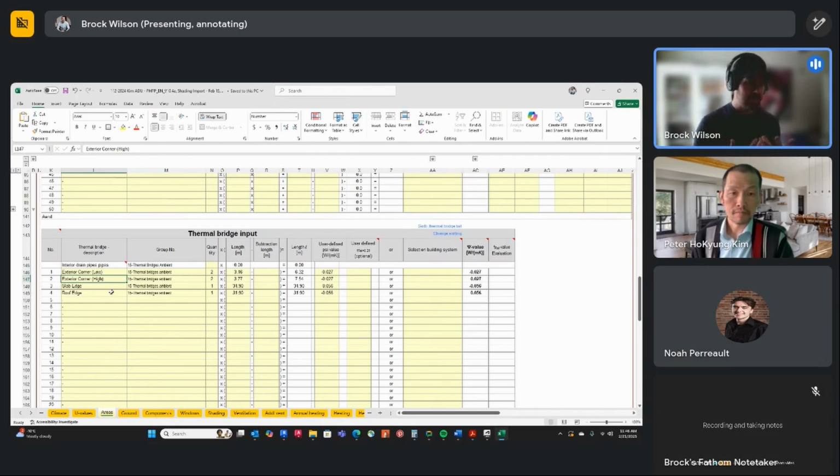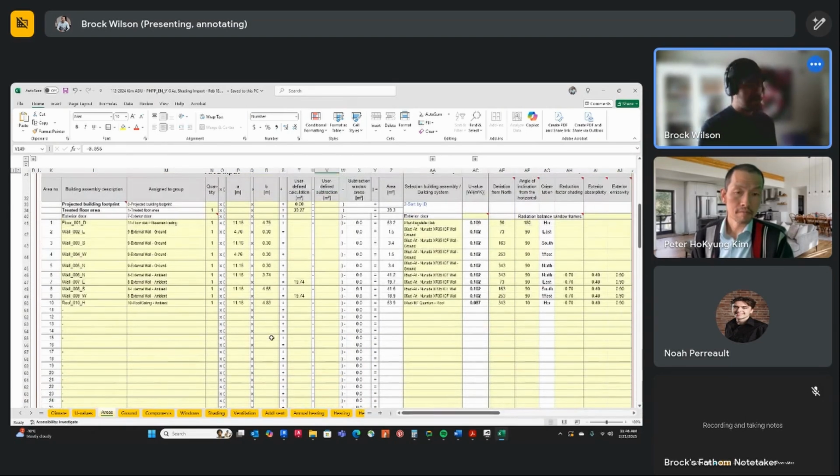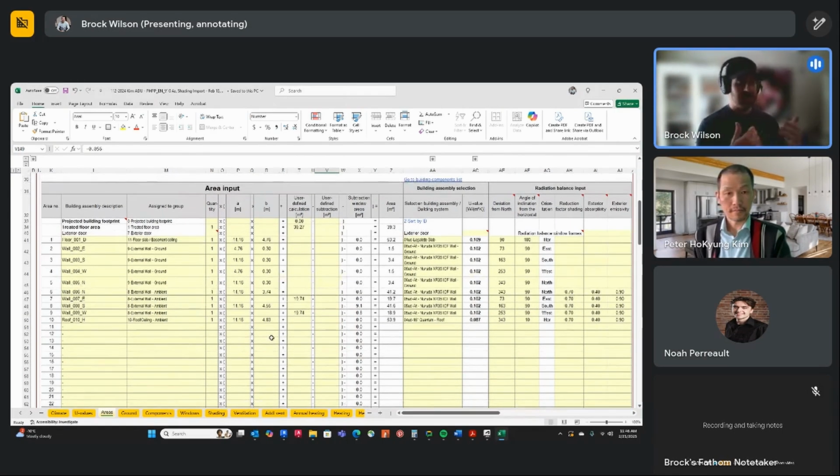These are all just right now somewhat assumptions in any case. The slab edge we've already detailed and firmed up, so that's concrete. The roof in itself, that overhang may be adjusted based on the composition, but by inputting those negative thermal bridges, it also reduces our heating demand rather than being conservative and using no thermal bridge, or a negative thermal bridge, right? So we want to take advantage of that.